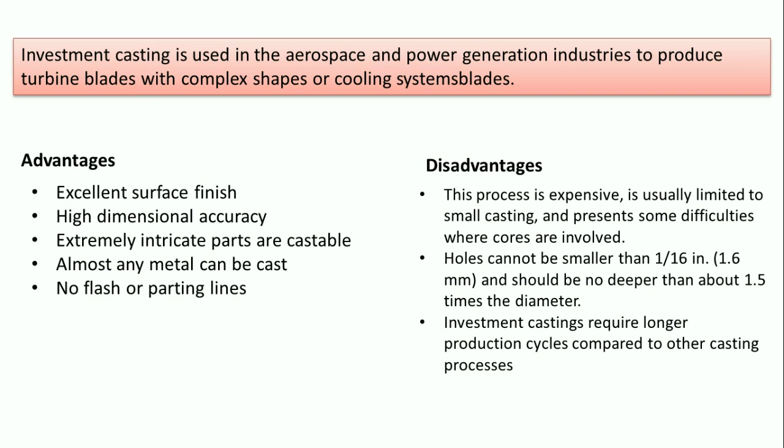The disadvantage is that this is an expensive process and usually limited to small castings. We face difficulty when we require castings with internal features. Holes smaller than 1.6 mm are not possible in this casting process. Investment casting requires longer production cycles compared to other casting processes.